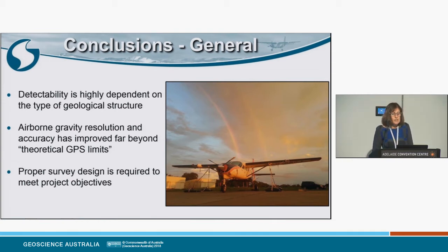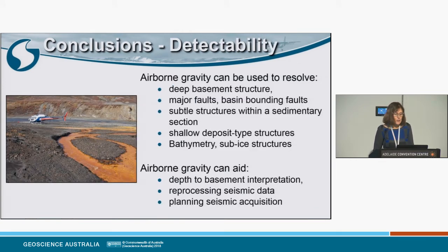So some general conclusions first of all. Detectability is highly dependent on the type of geological structure that you're measuring. Airborne gravity resolution and accuracy has improved far beyond the theoretical GPS limits that are often cited. And in order to do that, proper survey design is required.